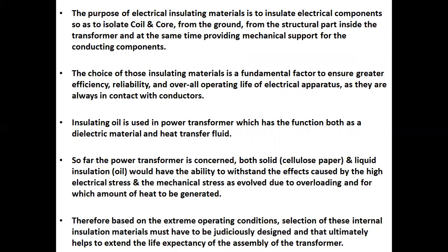The choice of those insulating materials is a fundamental factor to ensure greater efficiency, reliability, and overall operating life of electrical apparatus, as they are always in contact with conductors. Insulating oil is used in power transformer, which has the function both as a dielectric material and heat transfer fluid.